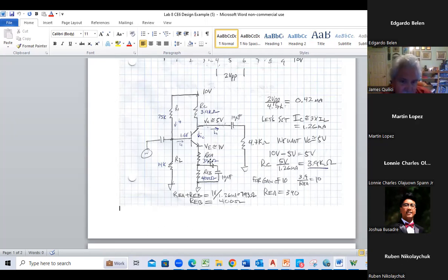The reason that is, we've talked about this before, is that a power supply has a lot of capacitors at the output to filter any noise. And so they can essentially be considered as a ground. So now essentially this node is at ground and this node is at ground. And so RC is in parallel with RL, the load.